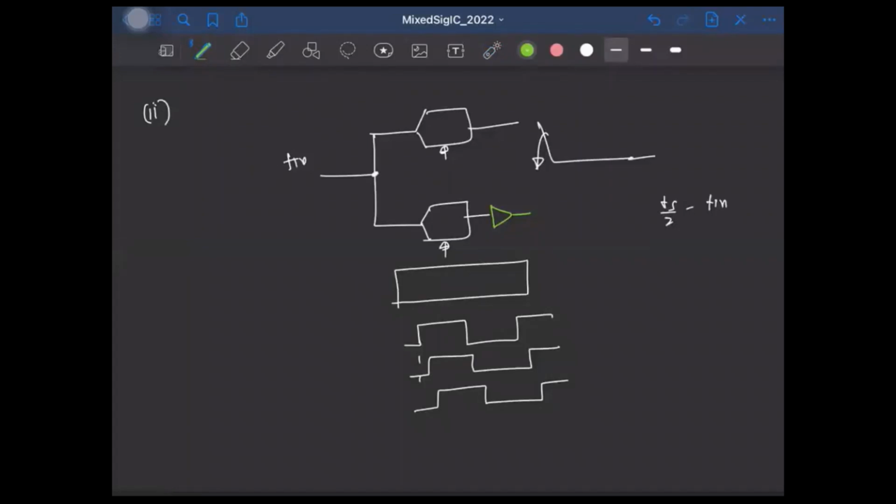And then let me say here, so do a block here, correct for the gain error, right? And after correcting for gain error, whatever residual tone that is at Fs by 2 minus Fin, that will be due to this timing skew. And then you can correct for the timing skew error, right? Or of course, you can do a combination of the two simultaneously to minimize the strength of the tone.